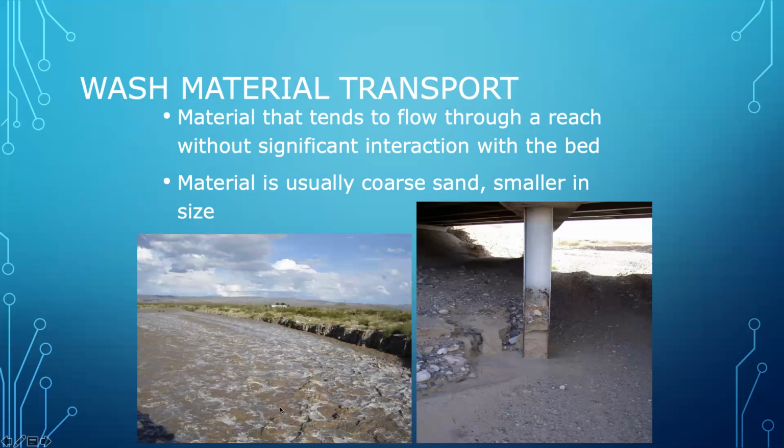The one with the water in it is taken from on top of the bridge, and the one without the water in it is taken from down in the stream bed. And during these higher flows, you can see that there's a considerable amount of relatively fine material, coarse sand that's been deposited on the backside of this support bend. And so at some point in its near past history, the bed load level was up here, and then as the water receded and washed away, it left behind the residue. And you can see quite a considerable accumulation of solids in this particular portion of the channel.